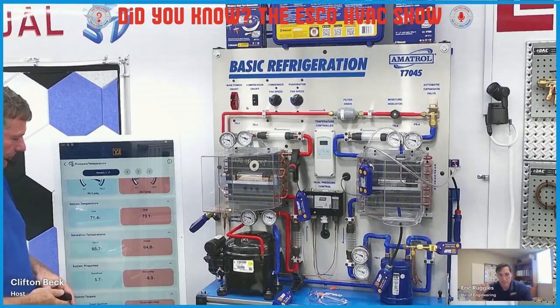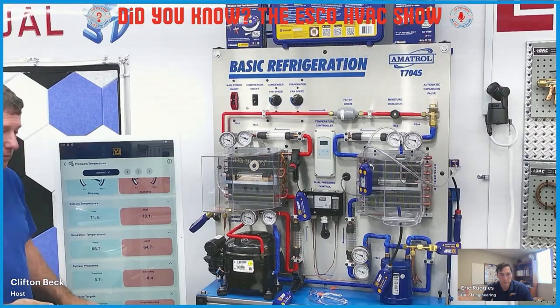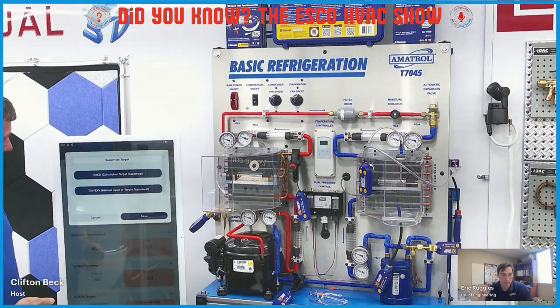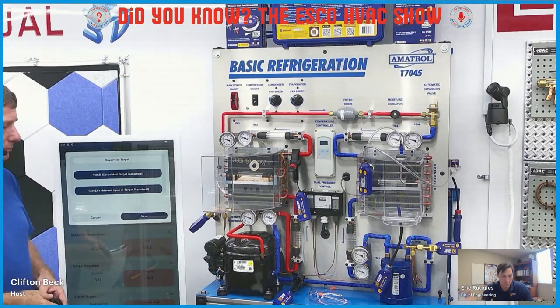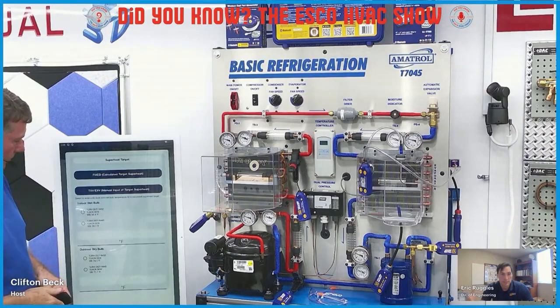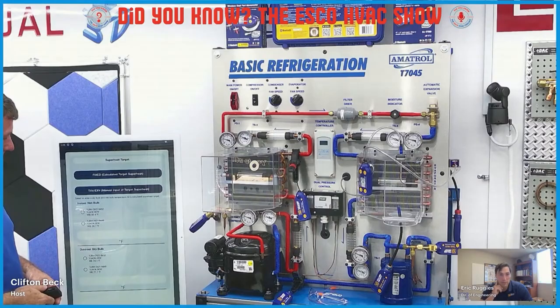Right. But at the bottom of the screen, it's hard to see with the camera at the moment, but there's system targets, and that's your target superheat, target subcooling, right? Yep, absolutely. You've got a nameplate of a system, or what you're typically doing for a type of product. On the superheat target, you can actually use an input, which is the bottom one, or you can use a fixed calculated superheat value. In that case, you can actually take the indoor wet bulb and outdoor dry bulb from your psychrometers. Yep. And then that'll auto calculate.